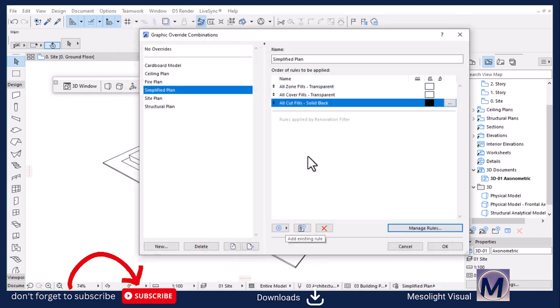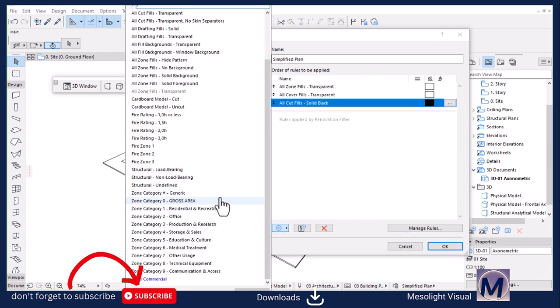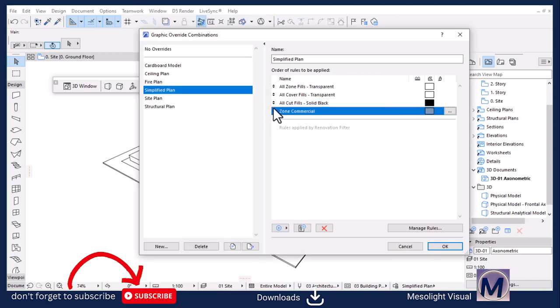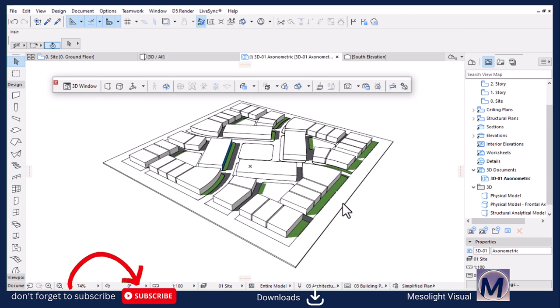Then we're going to add that rule here because it's not there yet. Let's click the plus. Let's find it down below. You see the newly created rule will be highlighted blue by default in ArchiCAD. So let's just click on it and then add. Let's use these two arrows to drag it to the top there. Perfect. And then hit OK.